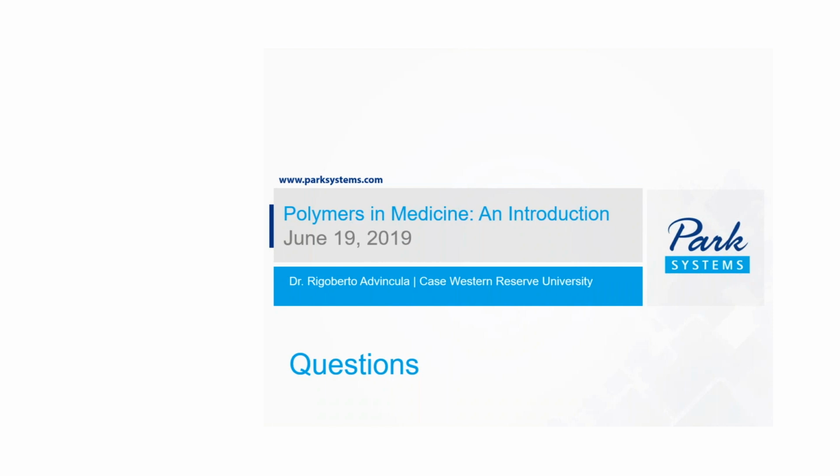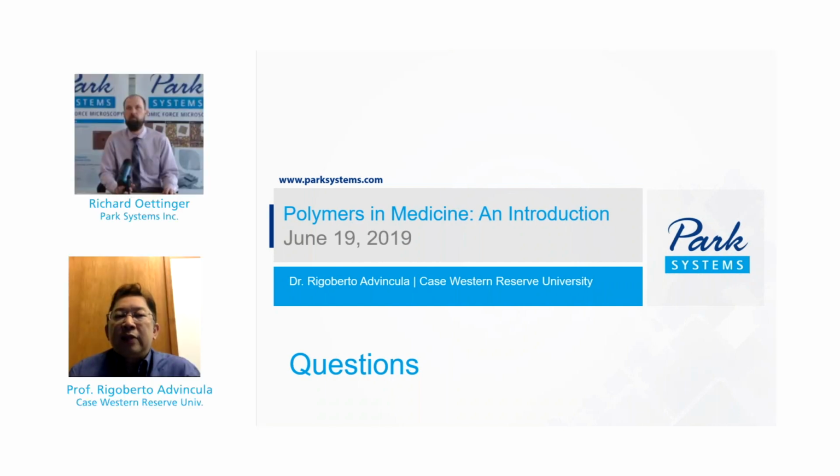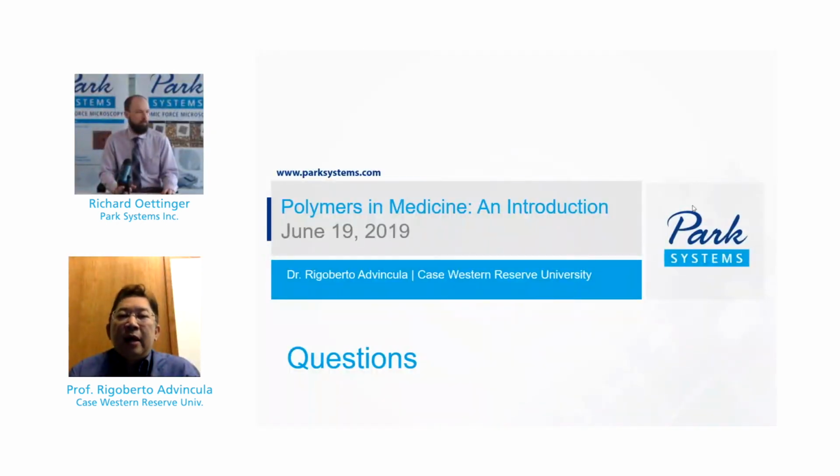When it comes to devices, we can be talking about injection molding and different types of formative manufacturing to create the exact shape. Some of these methods, based on extrusion, thermoforming, etc., are well known in the plastics field. For me, the high interest is in 3D printing, because with 3D printing, various types of polymers can be adapted to techniques like FDM, SLA, SLS, and prepared in the right shape.